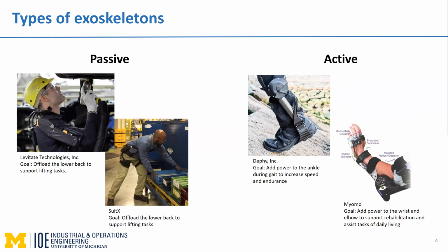When the kinematics of the human exoskeleton are misaligned, forces exerted by the operator are countered by forces internal to the human exoskeleton rather than being transmitted to the environment. And this inappropriate coupling creates inefficiency, it can increase fatigue and metabolic cost, and it can lead to injury. So the goal is for the wearer to perform the operational tasks they need.